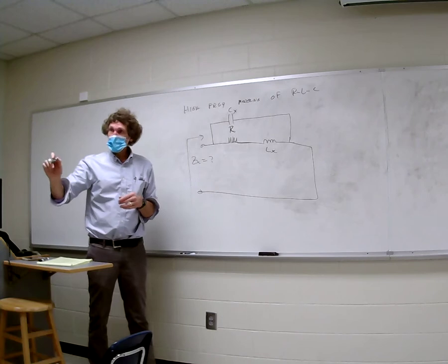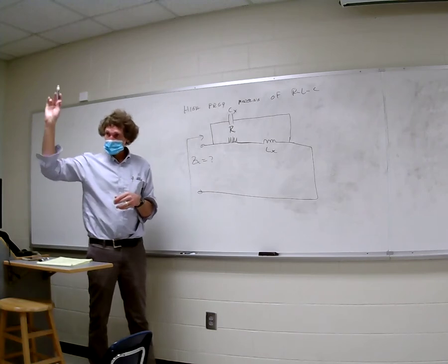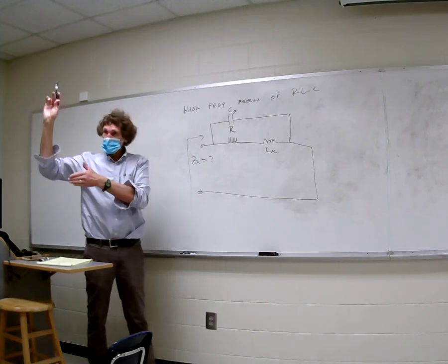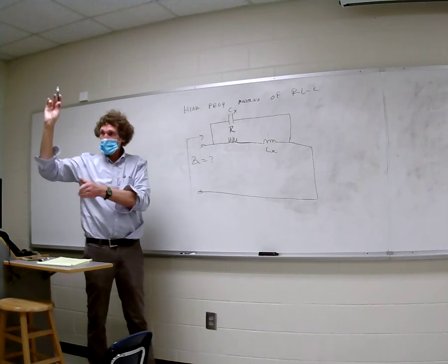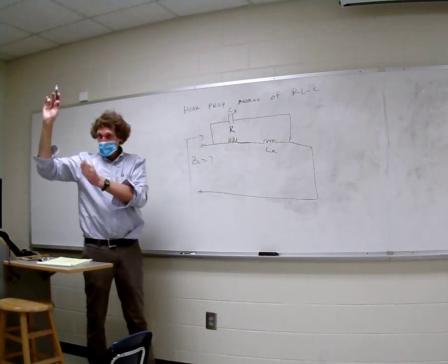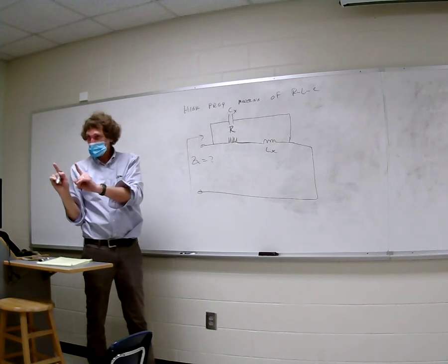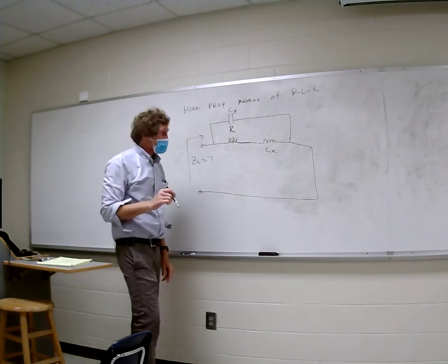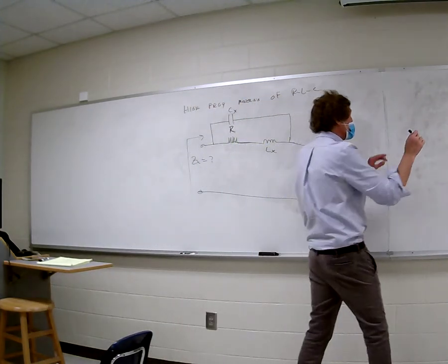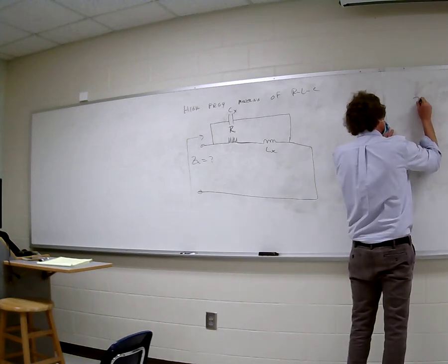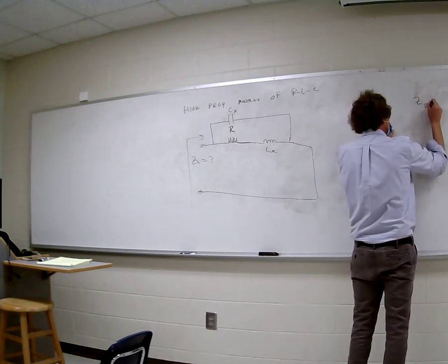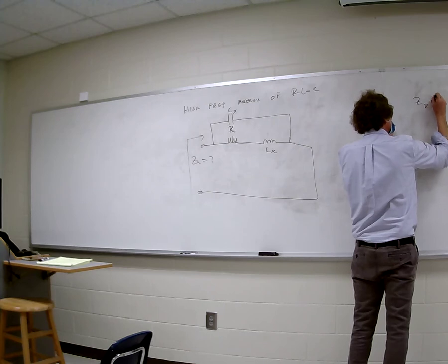You take 20 times the log of resistance, this is a Bode plot, and then you plot it versus the log. It's really the paper that takes the log. You know, there's 1, 10, 100, and stuff like this, all with equally partitioned distances. So when we do this, we take Z of this resistor, and this would be in dB.